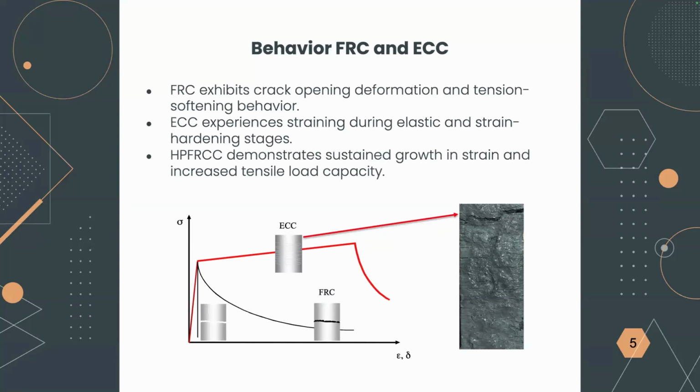So for example, if you would take a sample in the year 1960 and test it, you would expect a failure curve like this. This is the stress-strain curve, the tensile stress-strain curve. So let me explain it. First of all, how do we perform this test? We would take what we call a dog bone sample. Dog bone sample is simply a sample that looks like the dog bone, okay? And then we would place it inside the tensile machine with 2 clamps at the top, 2 clamps at the bottom. One end is fixed and the other end is moving.